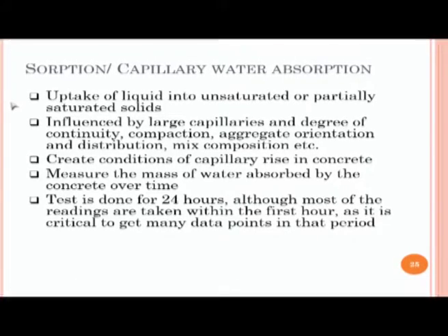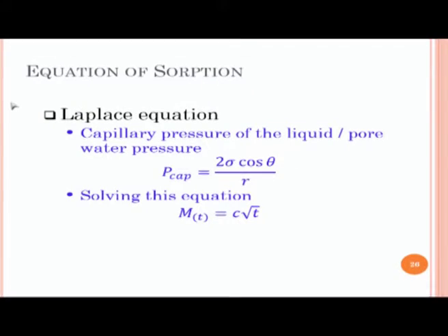What is important is whether these pores are connected or not. The aggregate orientation, the degree of compaction, the mix composition, all those will have an effect on the sorptivity or capillary water uptake. And this is one of the experiments that can be done very simply by creating conditions of capillary rise in concrete. I will show you how this is done.